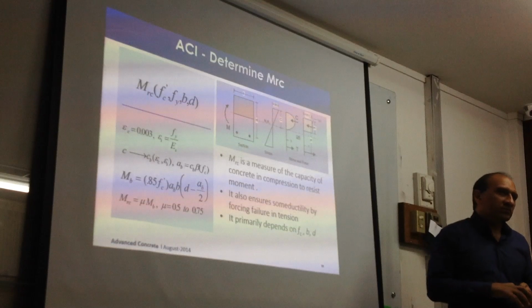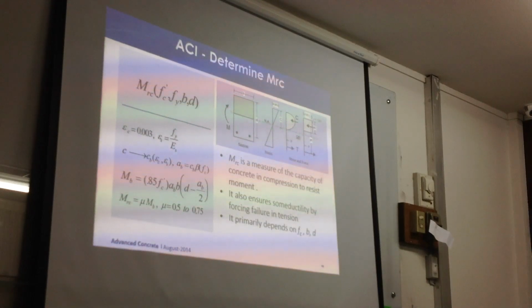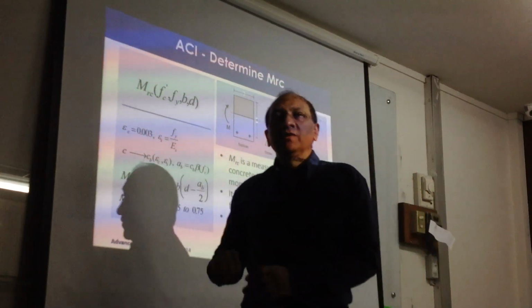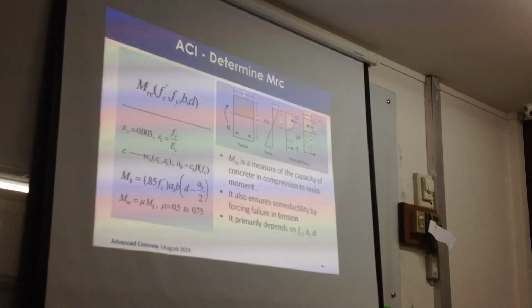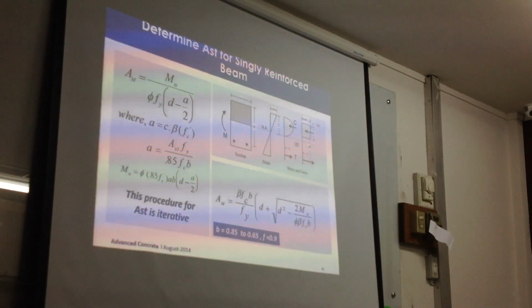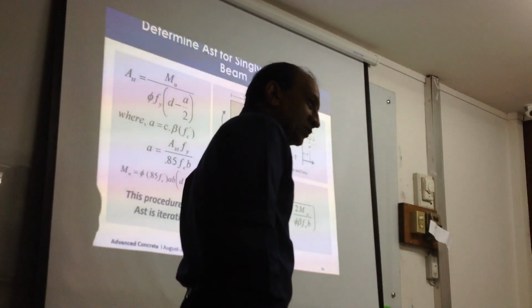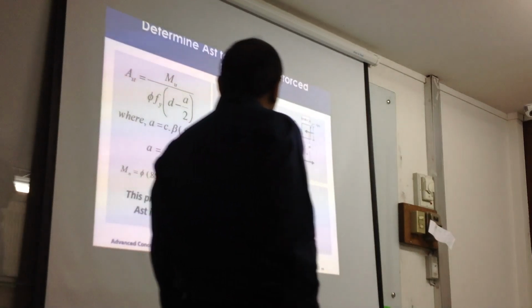In fact, they don't need to worry about this one because the strain 0.003, in actual condition, never actually comes. Right? But okay, they have developed a system, they need to follow it. So they say, okay, brittle failure we prevent it, which is a good thing. So we cannot put too much reinforcement in the beam, it's not good, especially for earthquake. Too much reinforcement is not good.